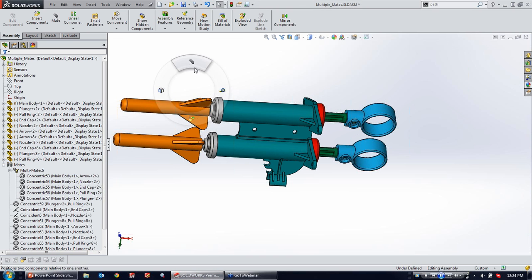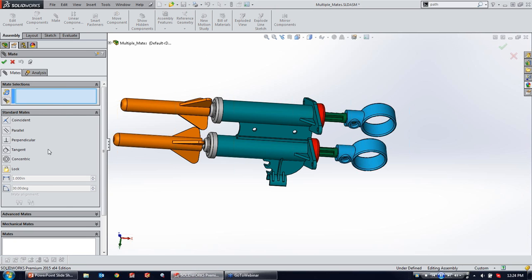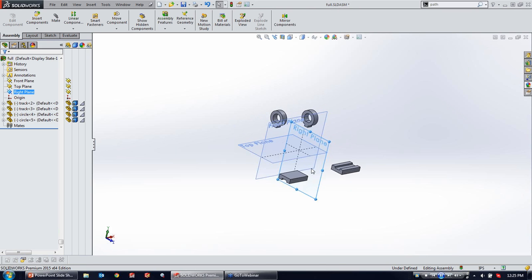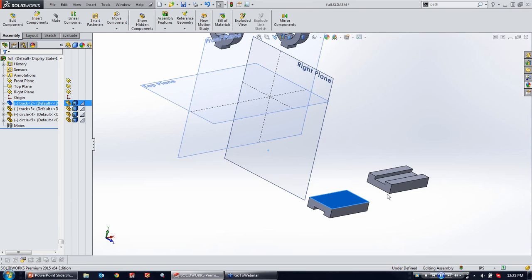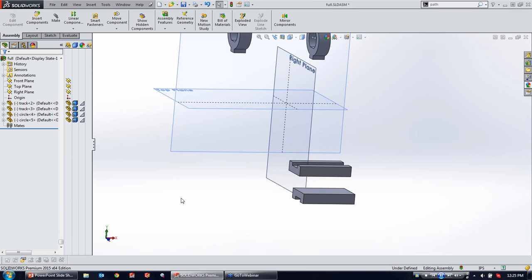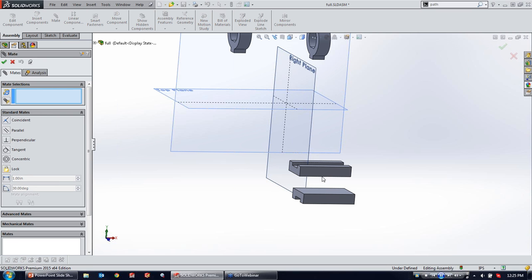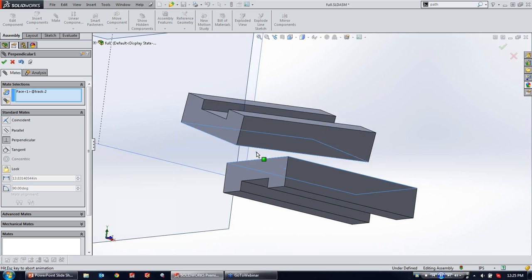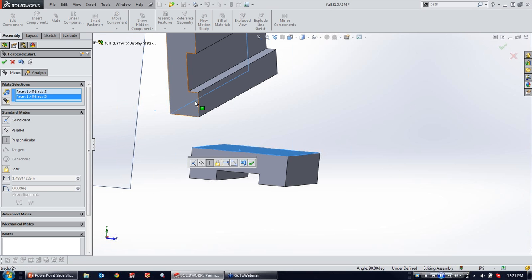We've pretty much gone through, just want to verify that we've gone through our standard mates. Distance and perpendicular, actually I'll launch those real quick. So this is going to be our next assembly, but I'll finish up with those basic mates just so we know for any beginners out there what we're talking about for these mates. So perpendicular mate, we'll take two faces, not a plane, two faces, and throw a 90-degree angle at them. You still have two range of motion, but that's always going to be locked down. But those two faces are perpendicular.